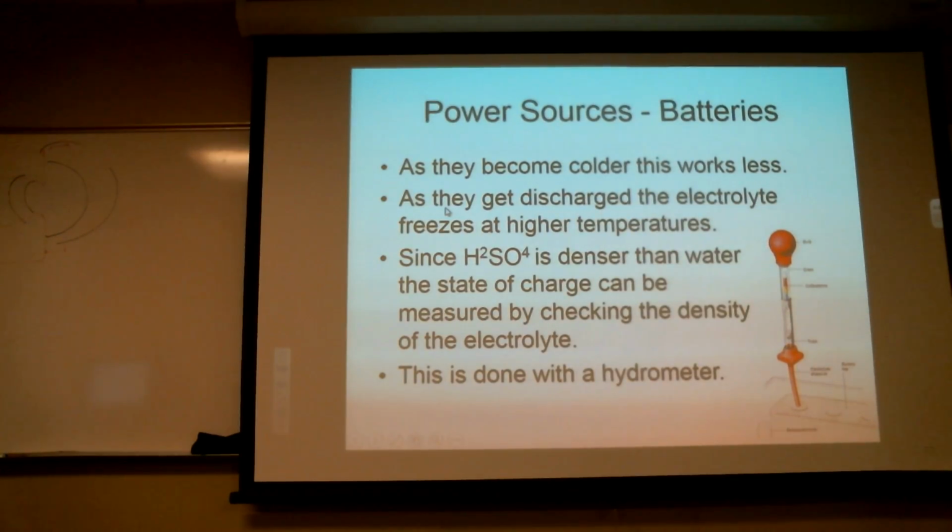The truth is, you guys are going to go through this entire process. I want you to measure every cell, measure the voltage, put it back on the charger. Every cell, measure the voltage, put it back on the charger. In truth, with the hydrometer, for the batteries you can actually get into, which is only going to be one type of aviation batteries, they've eliminated the ability to get into batteries in the automotive industry. Most of the motorcycle industry as well. They've all gone to fully sealed absorbent gas mat type batteries.